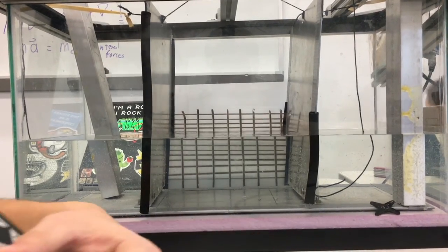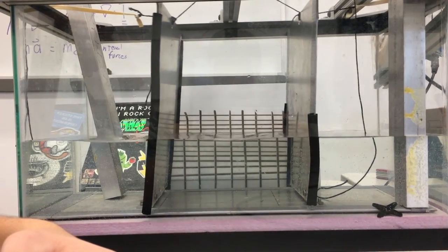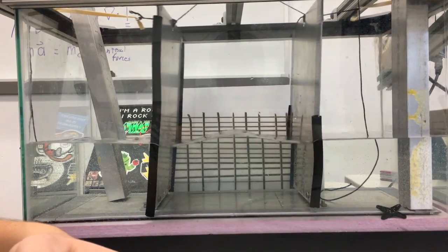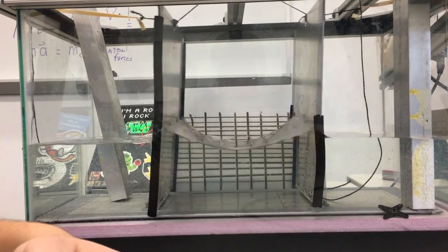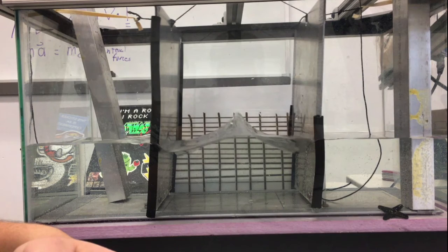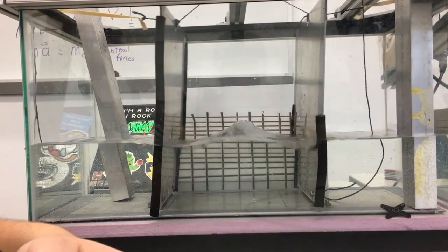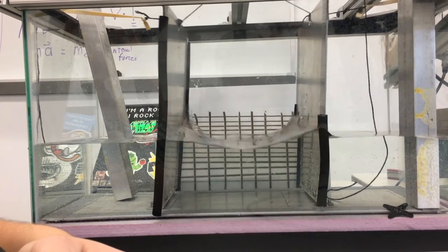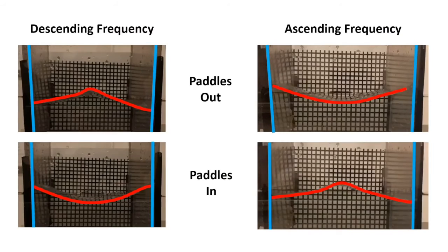Another thing that G.I. Taylor was investigating was a transition from two-dimensional stability to three-dimensional instability in standing waves. In the paper by Penny and Price, standing waves of finite amplitude were analyzed, and they concluded that the peaks of these standing waves could form a sharp 90-degree crest. At that point, they would become unstable due to the downward acceleration near the crest necessary to maintain their shape exceeding that of gravity. This instability caused the wave formation to break from a two-dimensional pattern into a three-dimensional one, and consequently lose most of the wave's amplitude. This can be seen on our apparatus and agrees well with Taylor's experiment.